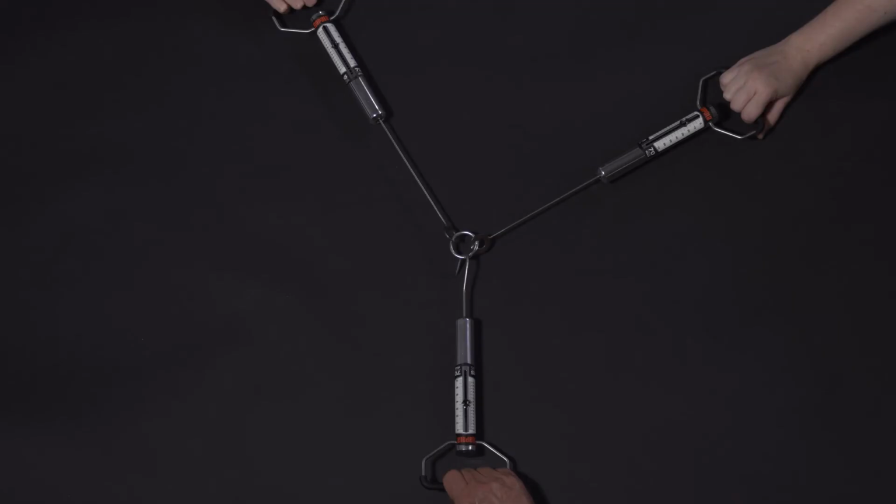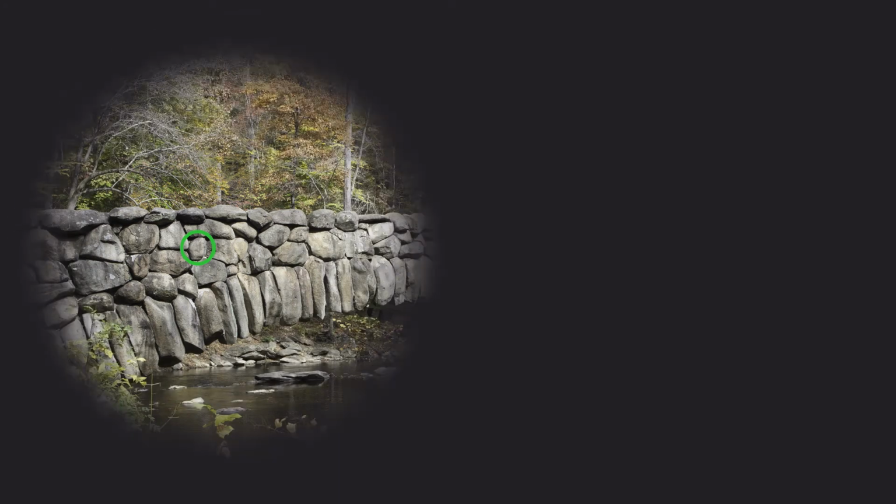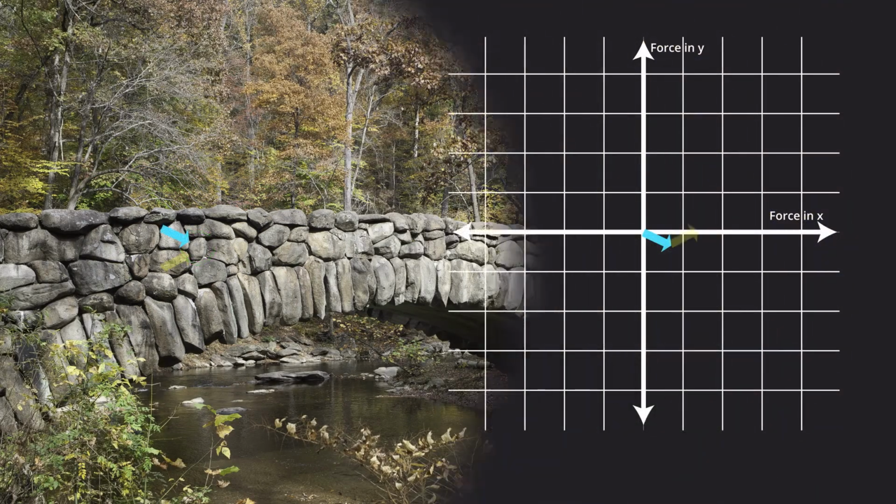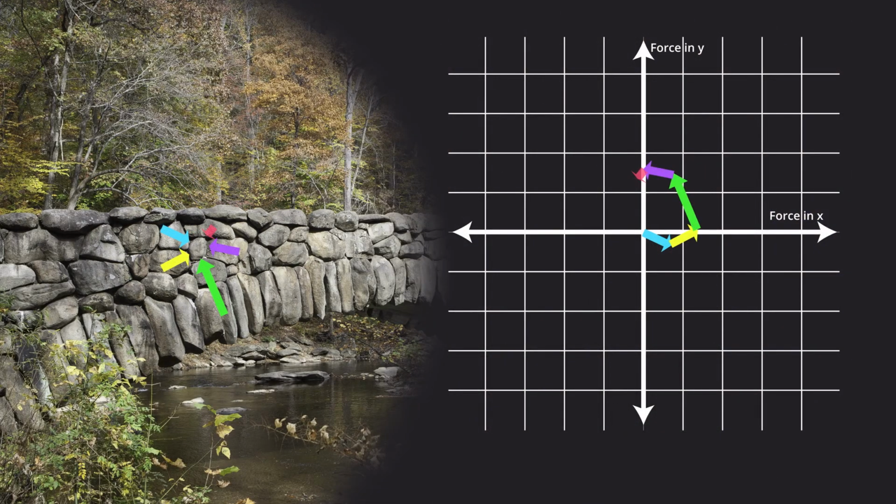For simplicity, this video has focused on well-defined points that experience tensile forces. However, the principle we just stated applies to arbitrary points, such as this stone in a large bridge, and it describes how the compressive forces acting on it must be related to each other so that it does not move. If an object of interest is large enough that the forces acting on it could cause it to rotate, we must treat it as a rigid body rather than as a point. And that is the topic of the next video.